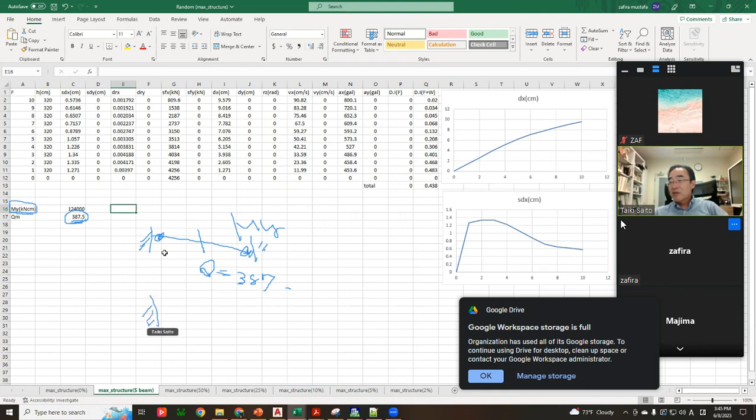Then you put the metallic damper in the middle. You design metallic damper by bilinear, yielding by Qy. But Qy must be less than 387, because you want to dissipate energy at the metallic damper.